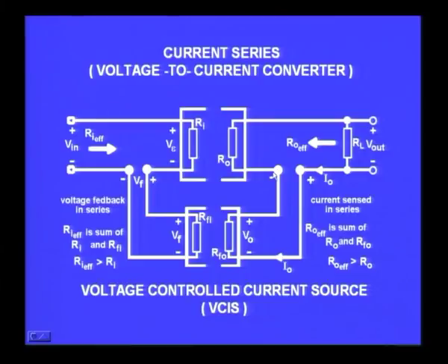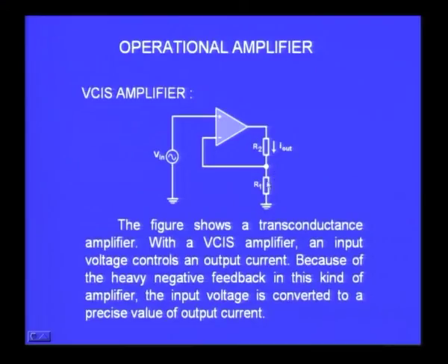And now let us try to look at the circuit based on this. So what you see on the screen is a very simple op amp voltage to current converter. In the feedback, this is a negative feedback, you can see that you have an R1 and an R2. So whatever current is flowing through R2, that and R1 form a potential divider, and this voltage is applied here in series with the input voltage, and therefore this is exactly the same as what we discussed a moment ago.